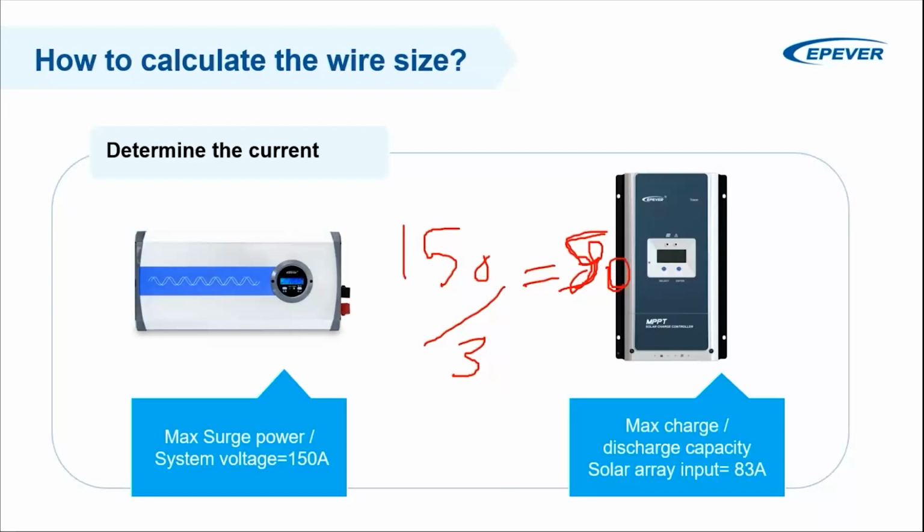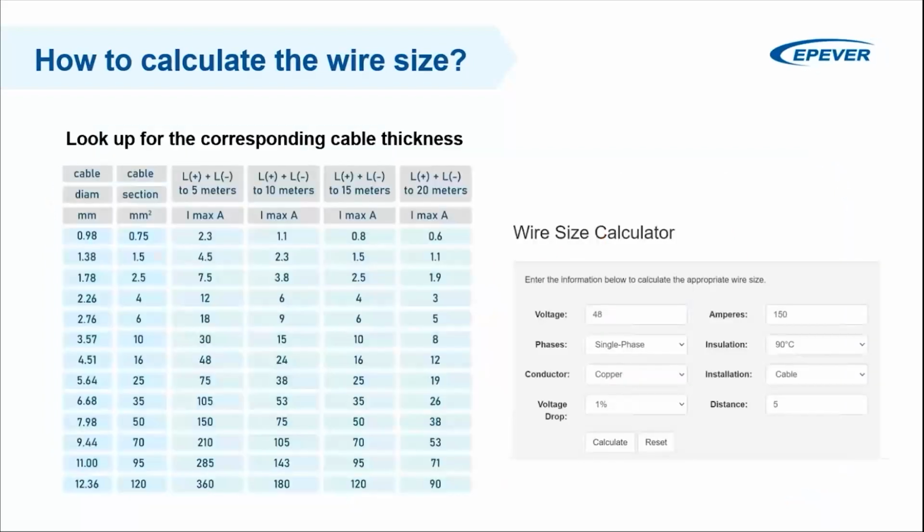And this is the thickness of the cable in square millimeters. And it's the same if you divide the amount of current that you got, for example, for the charge controller, then you will get the same for the cables. So a straightforward and easy thumb rule is to divide the current by 3, and what you get is the cable thickness in square millimeters.